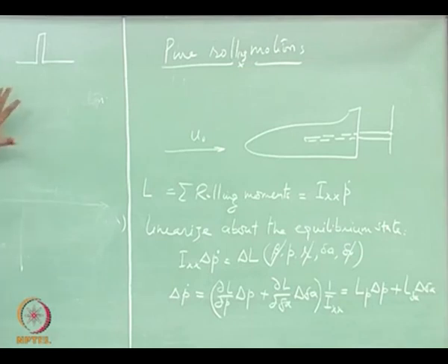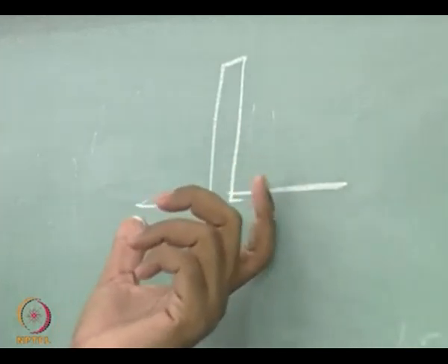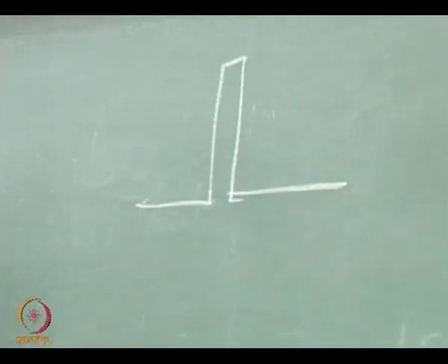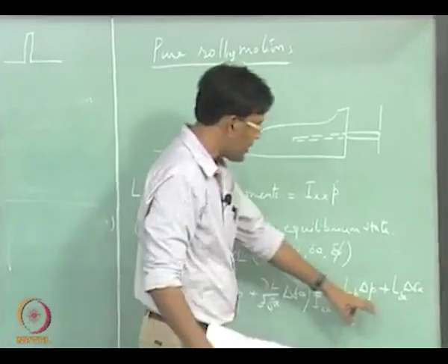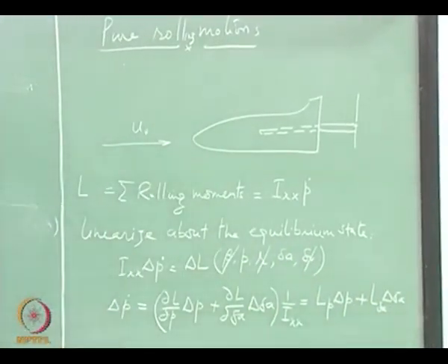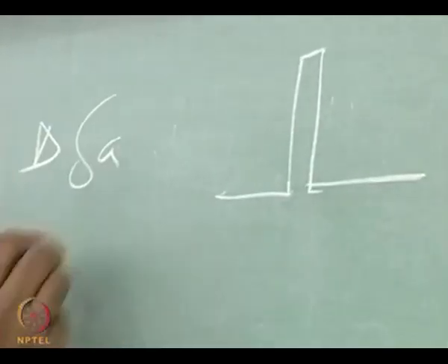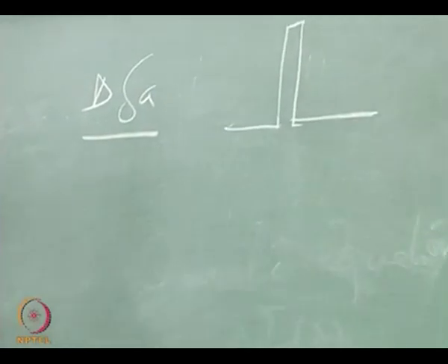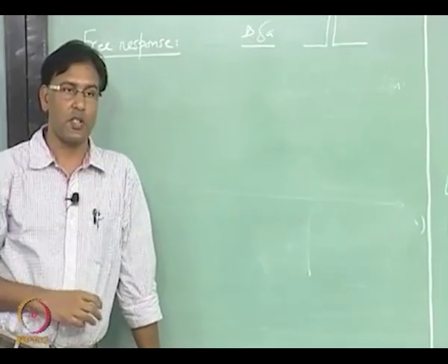Okay. So there are two ways of doing this. One is to give a perturbation in the initial condition and simulate the aircraft linearized equations of motion. Second thing is you can give an impulse, or a pulse of very small duration, to the control input. Okay, so it acts like a disturbance. You are giving a pulse to aileron and that will initiate the roll motion.